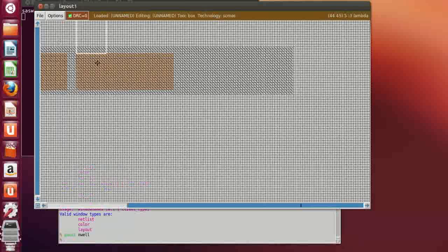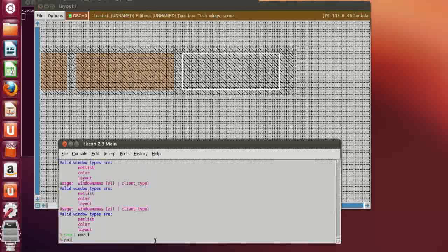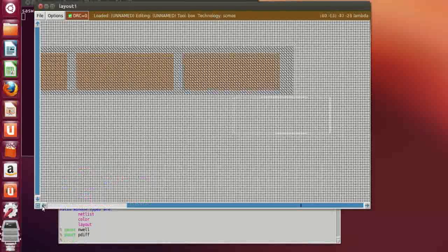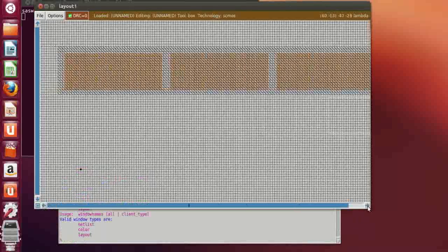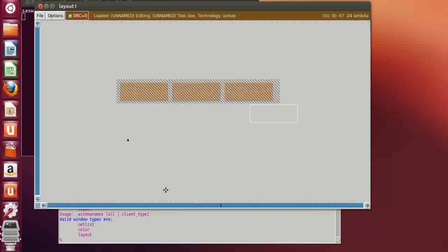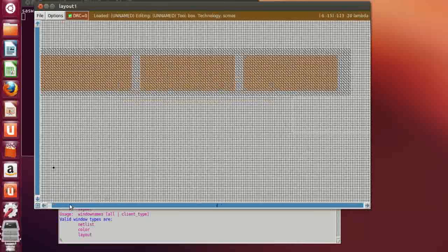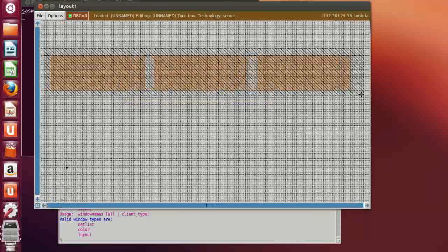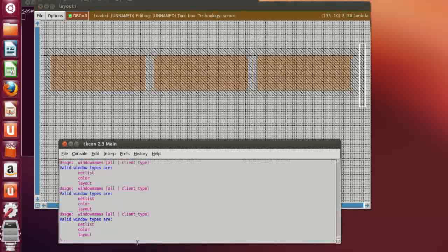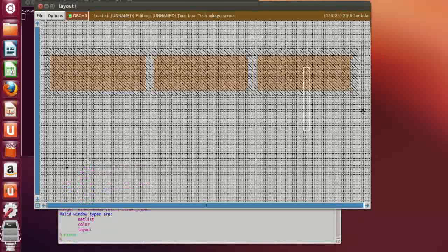Now of the same area, first select from here, of the same area we have to place the third P diffusion. So paint pdiff. Okay, now just for uniformity, we can remove this extra layer. So select the area and type erase. Now this is the PMOS layer.